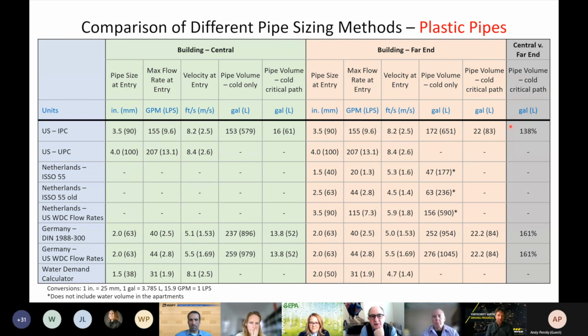Yeah, as soon as we put the riser in the middle, we just cut the critical path and all the other flow paths into half, more or less. So for the German sizing, that makes a big difference because when we are sizing with regards to the available specific pressure loss per meter, we can allow to waste more pressure per length of pipe. Right. And therefore design smaller.